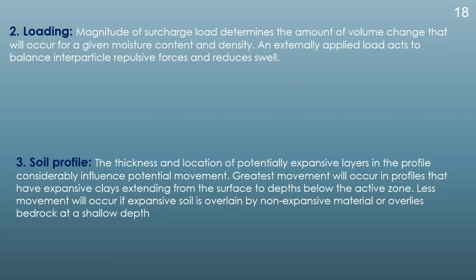If this is a soil profile, and if a large amount of load is acting on this soil, then the soil swelling will be very less, because the soil will exert a pressure which will be counterbalanced by the surcharge load that comes from the overburden load of this building. If there is no load or a light amount of load is present, in that case a higher amount of swelling will take place. So, the last one comes from the soil profile.